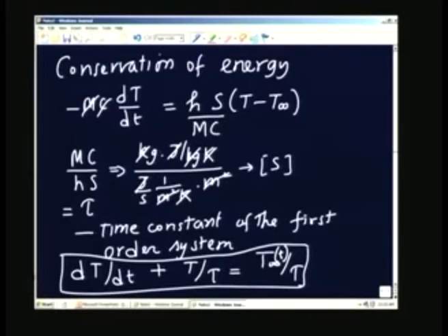It could be a different function, and also we know that the temperature of the sensor initially, at t equal to 0, is Ti. So, we have the equation governing the problem, a first order ordinary differential equation, with the initial temperature T at t equal to 0 equal to Ti. The solution of this is essentially what we are going to look for.